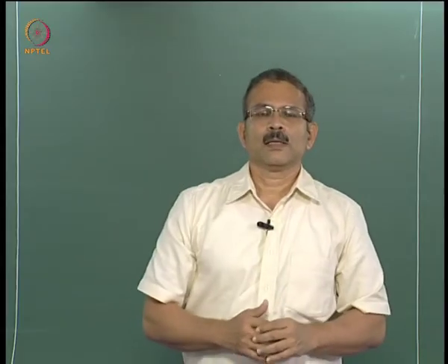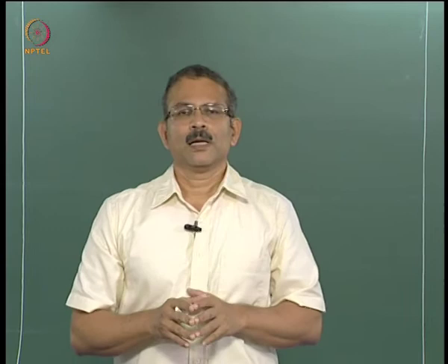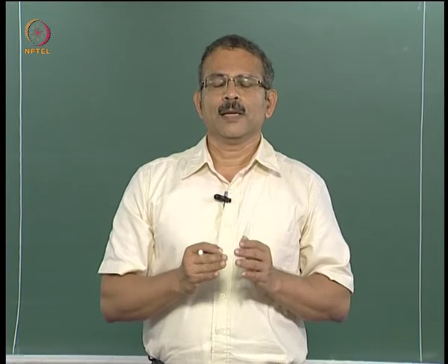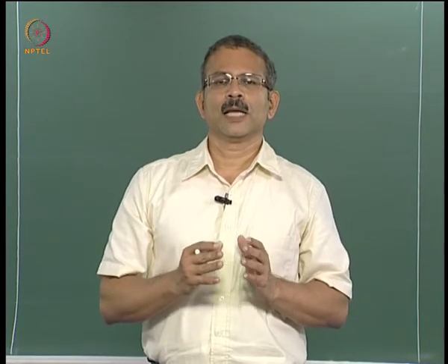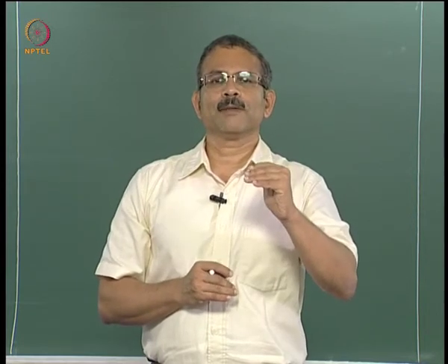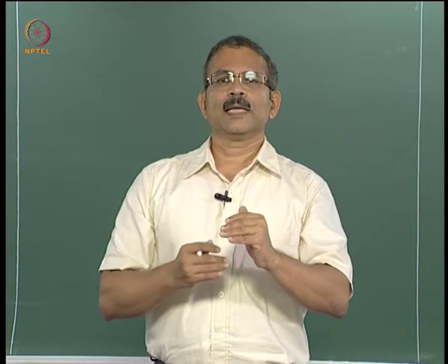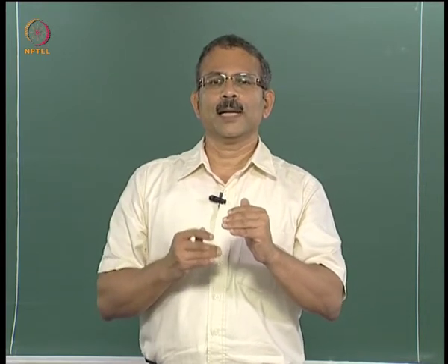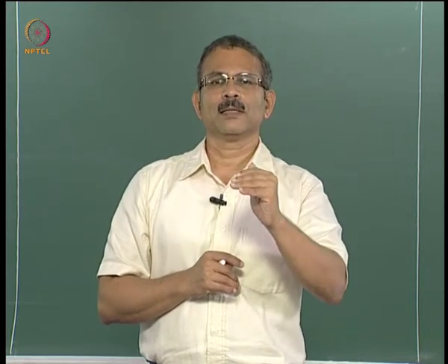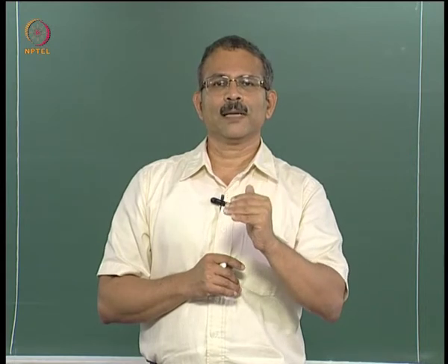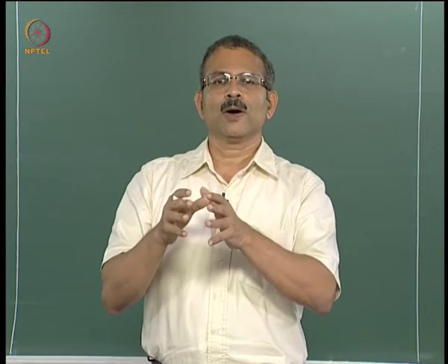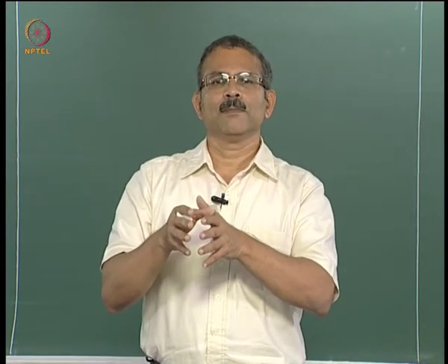Now since we are at the end of the lecture, let us make a summary of the important points. In this lecture we developed the energy balance equations approach for modeling devices. We showed that the Boltzmann transport equation is equivalent to an infinite series of balance equations. This series is terminated after 3 balance equations, namely those of the carrier concentration, the momentum density and the energy density, and this termination is achieved by a closure relation for the energy flux that enters into the energy balance equation.